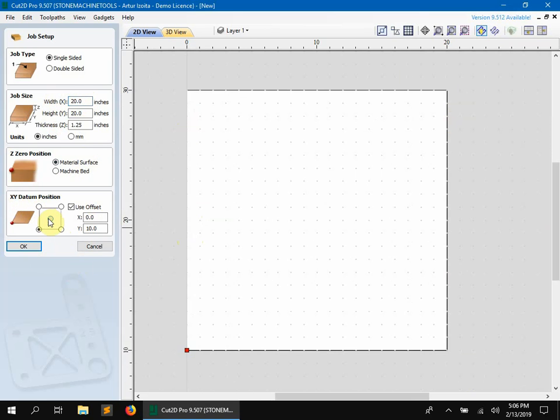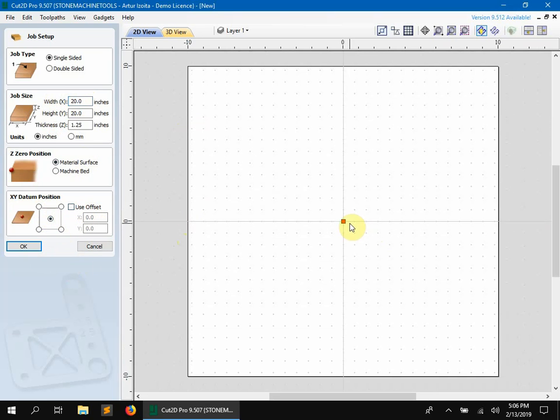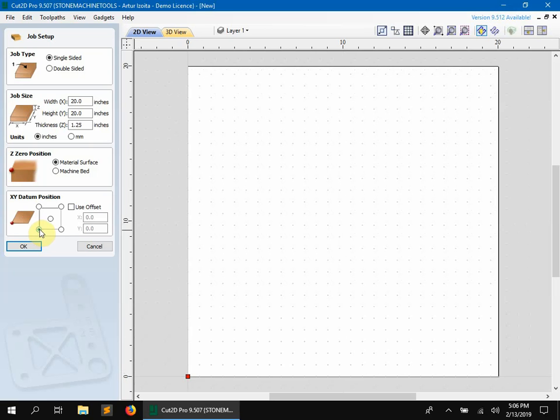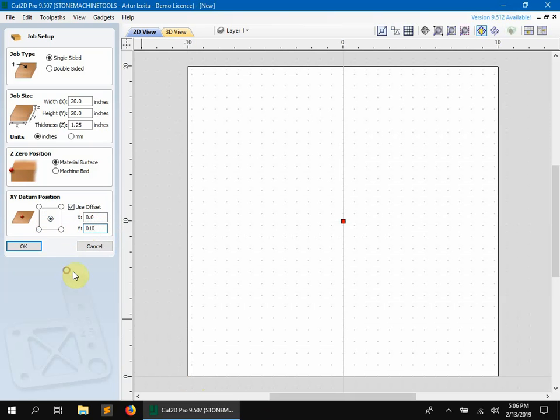You pick the origin position. This is the position where the 0, 0 point of the drawing is. If I select bottom left corner, the 0, 0 point will be bottom left. Usually we set it to the bottom middle of the sink. As you type in the numbers, the lines on the sides will show you where the origin is.